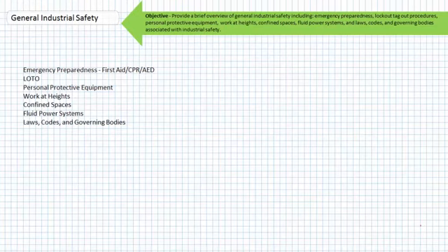Additionally, realized systems are often remotely interconnected, and certain commands can override manual controls. These means of operation must also be locked out. Lockout means achieving a state of zero energy while the equipment is being serviced, and it must remain so until returned to service. The concept of tagout is different from that of lockout.